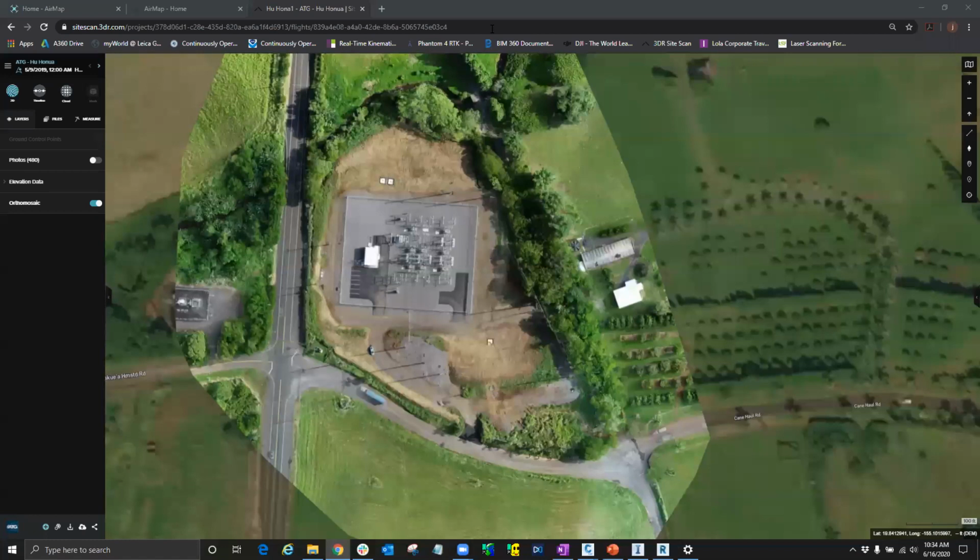And then Jeff is asking, what about an obstacle to avoid, such as a tower in a flight area? So some of the later drones have obstacle avoidance built into them, like our Phantom 4 Pro. It'll start beeping when it notices an object within 15 to 20 feet. It'll start beeping on the controller to get my attention. And on the controller, you can have different override settings. So I could override and manually fly.